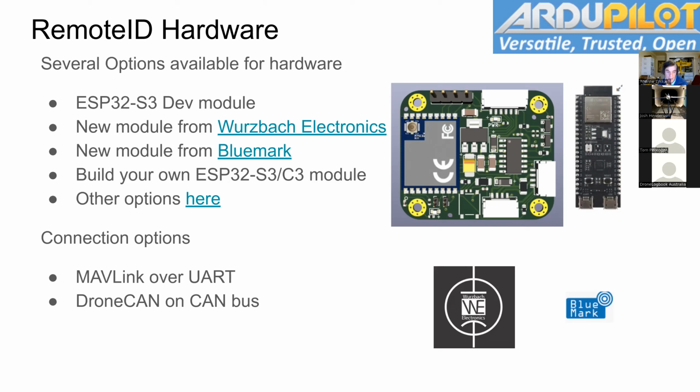What I expect is going to happen over the next few months is that custom carrier boards are going to come out for the ArduPilot, and those custom carrier boards would have remote ID built in. Hopefully using a remote ID that's compatible with the ArduPilot remote ID firmware on the module, so ESP or NRF, and that will be how things are locked down. But of course, there are no custom carrier boards like that today.